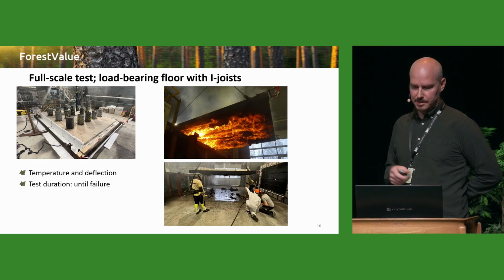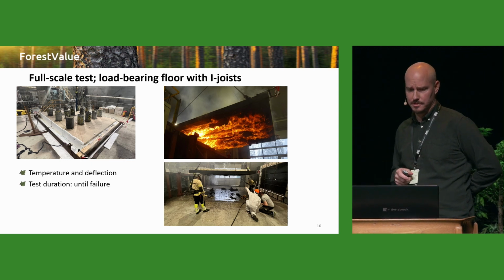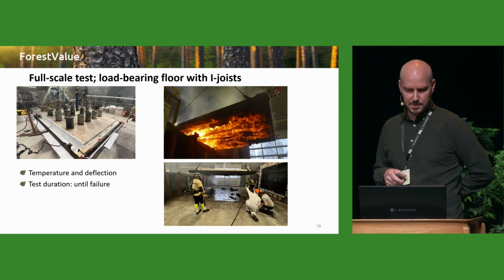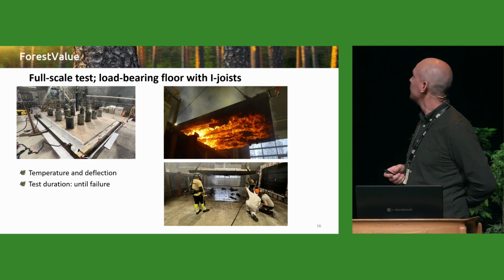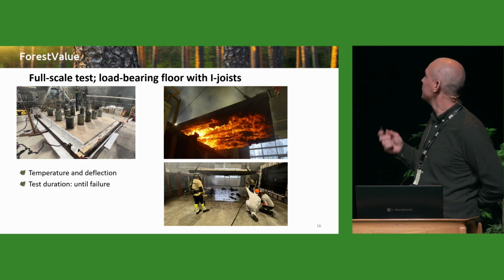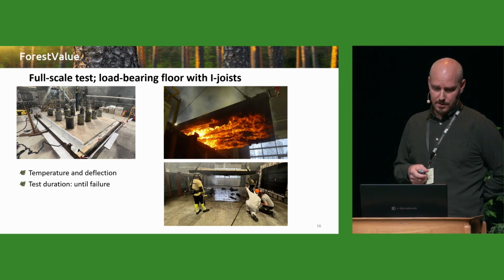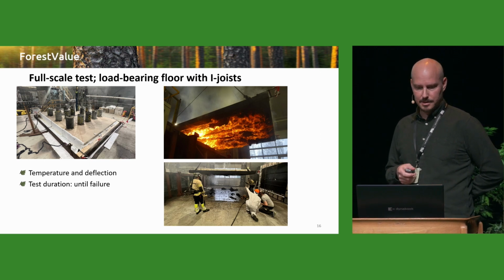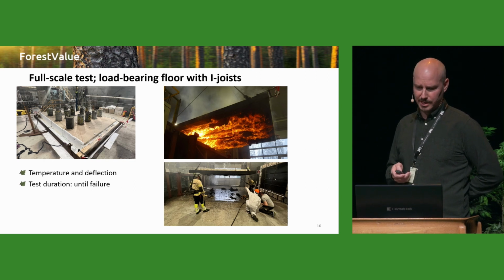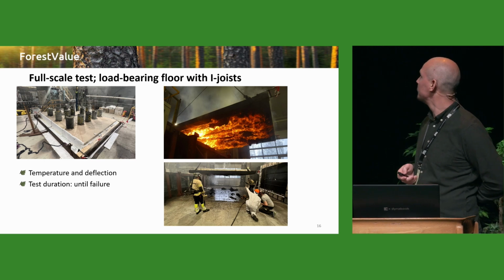Also did a similar test as the CLT, but with load-bearing floor with I-joists. Same setup. We have the dead weights to the left, and during liftoff, you can see the exposed side on fire. Also, for this test, we measured the temperature and deflection as you do in the test standard for testing these kind of constructions. And we ran the test for, I think it was 74, 75 minutes before we ended it.